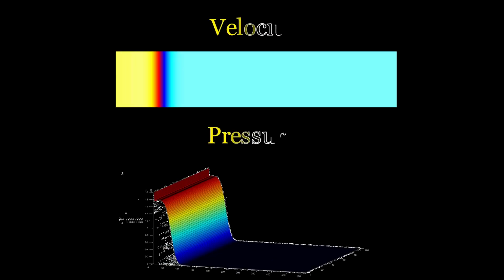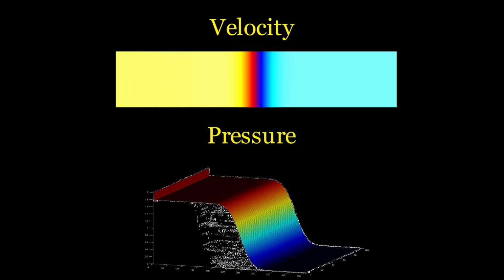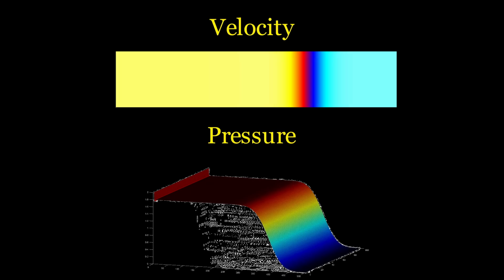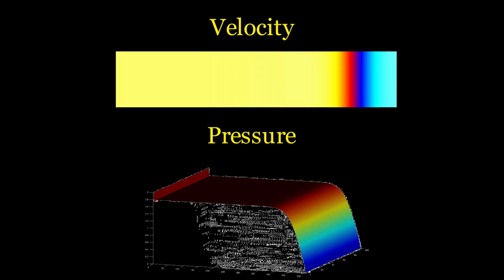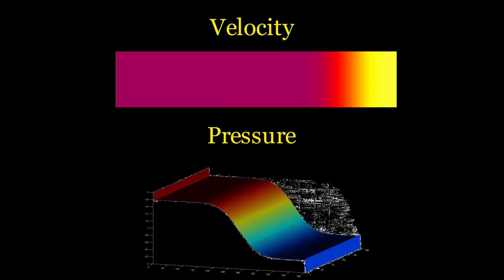At this point, we have a wind tunnel that we can see the velocity change in as time progresses. It has a starting value of 0 everywhere, so it will take a few seconds to find its stable velocity, since the pressure is bouncing back and forth in the tunnel until it also stabilizes. If you want to see particles, you can do this with a forward advection from either your Euler or the RK4 method.